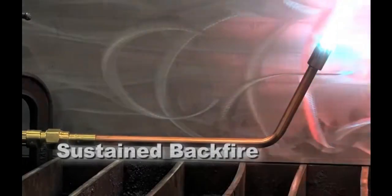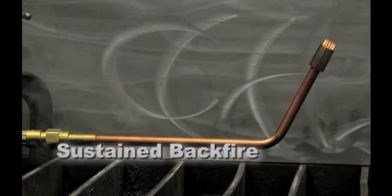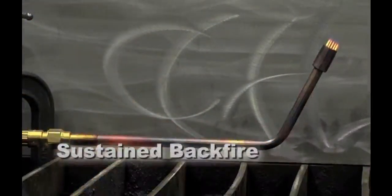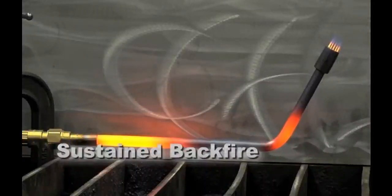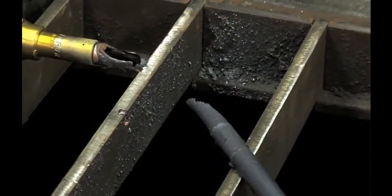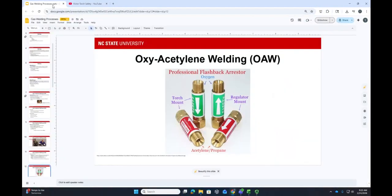The last event is a sustained backfire. This is when a backfire occurs and continues burning in the torch. This condition may be accompanied by a popping sound, followed by a continuous whistling or hissing sound. Some of the causes for this are improperly maintained equipment, overheating of the equipment, or improper pressure settings for the equipment being used.